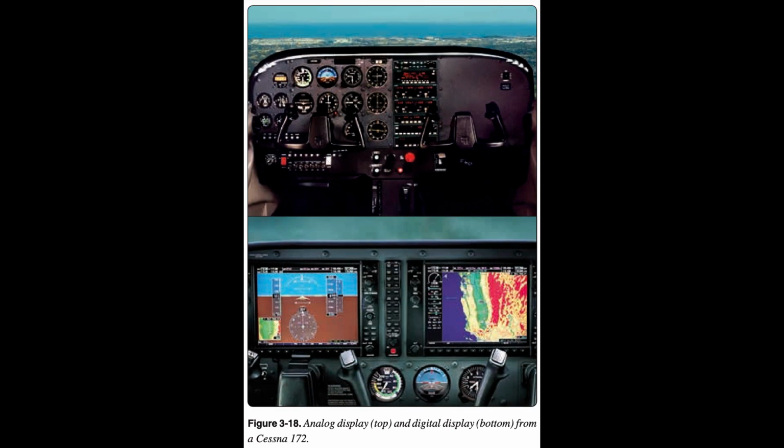Until recently, most GA aircraft were equipped with individual instruments utilized collectively to safely operate and maneuver the aircraft. With the release of the Electronic Flight Display (EFD) system, conventional instruments have been replaced by multiple liquid crystal display (LCD) screens. The first screen is installed in front of the pilot position and is referred to as the primary flight display (PFD).